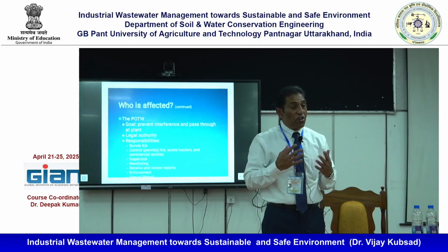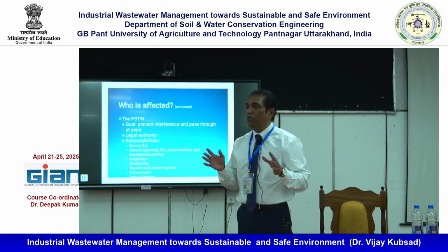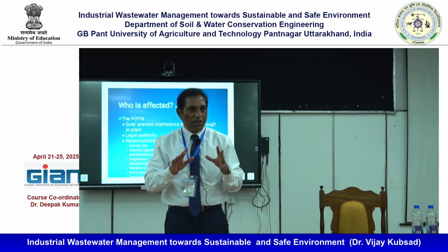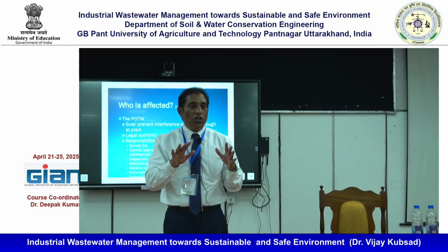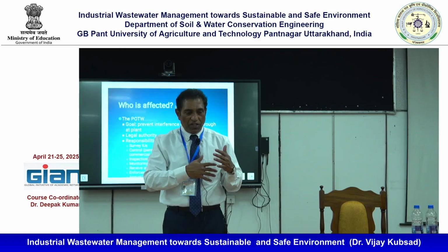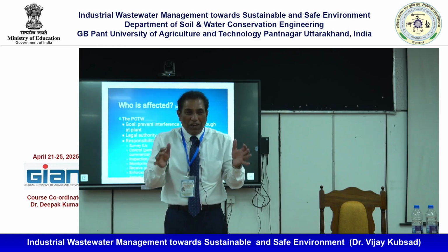There are industries that say they don't have toxics. There are some food industries that use cleaning all the time, and they have BOD, TSS, and a flow. They can collect it, remove the suspended solids, and then discharge. They give a little pre-treatment.